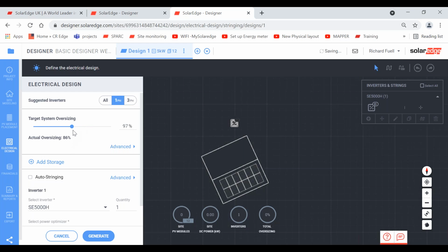So we've actually changed the inverter for this job. If I move up to here, it changed to a 4 kilowatt inverter. If I come higher, it's now changed to a 3.5, and just in there, we've got the 3.68. So generally speaking, on a residential property under G98, you would be using a 3.68 inverter. So just be sure that you're selecting the right inverter, and if it's presented to you, then you can change this to how you want to do.